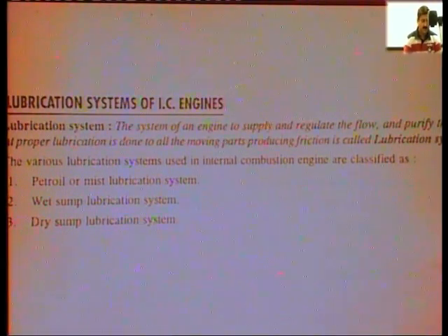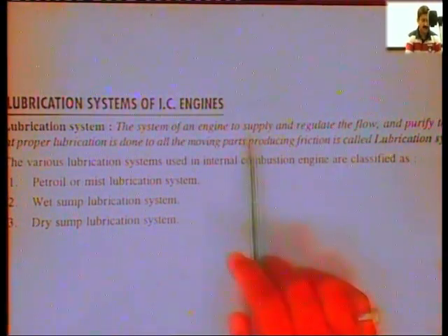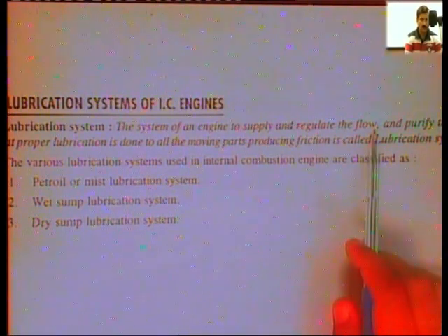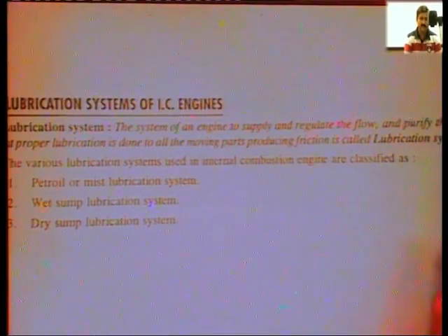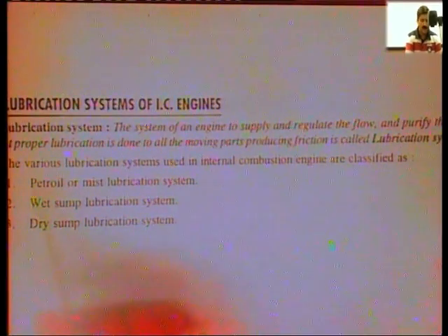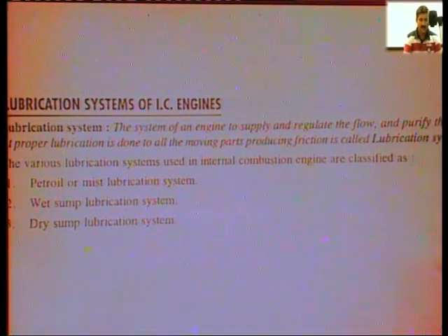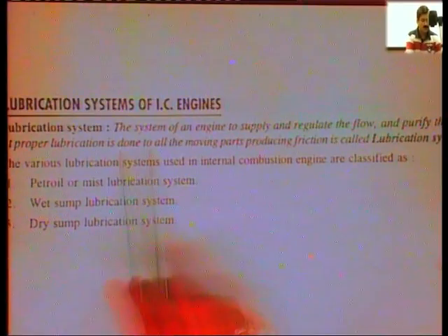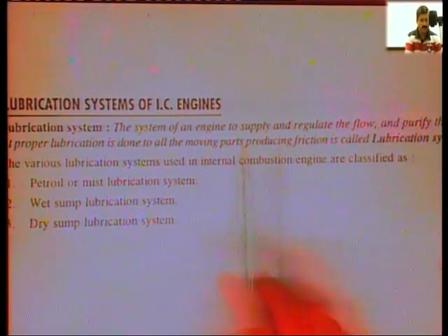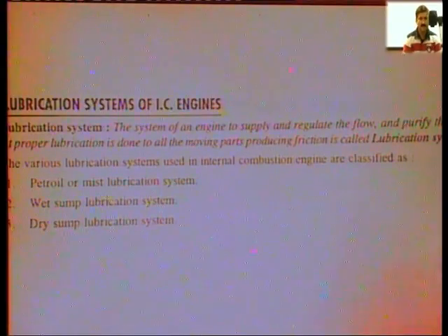There are some purposes for lubrication system. First is to supply and regulate the flow and purify the oil. Purify means the detergency property, purify the oil, and also, as we will see later on, there are filters employed for purifying the lubricating oil, so that proper lubrication is done to all the moving parts producing friction.